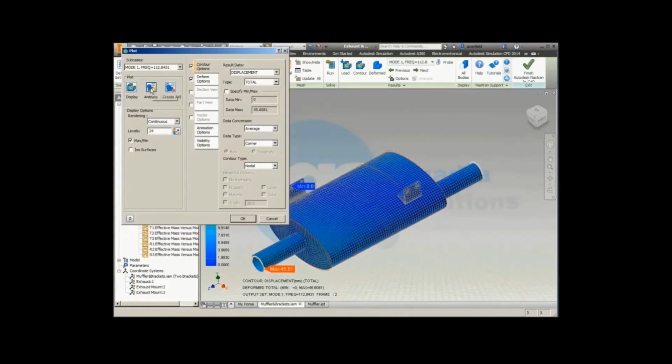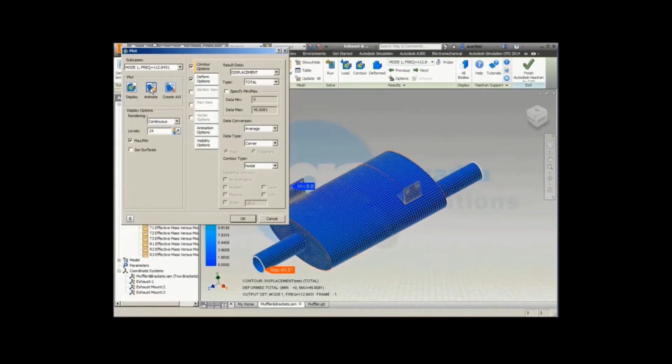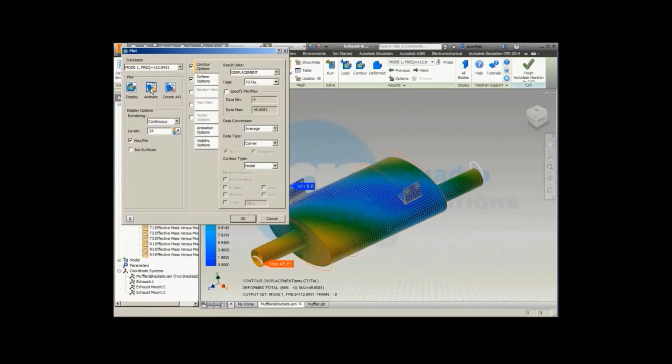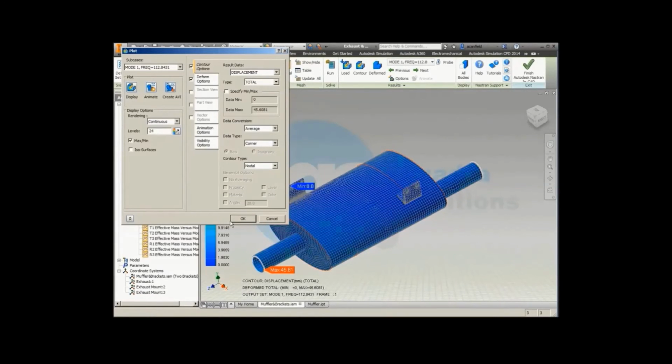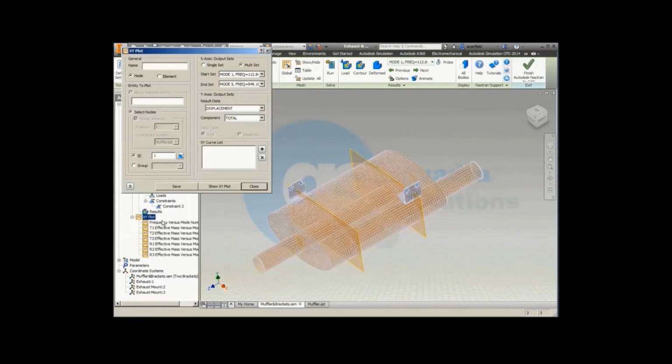So using the shell element is one of the advantages of being able to create a surface body. The shell element will use fewer quadrilaterals and reduce the number of nodes that are needed. So that will help speed up the analysis further down the line. And being able to use the welded contacts to link the solid elements and the shell elements together, it's just a way of generally increasing the speed at which models can be put together and analysed.